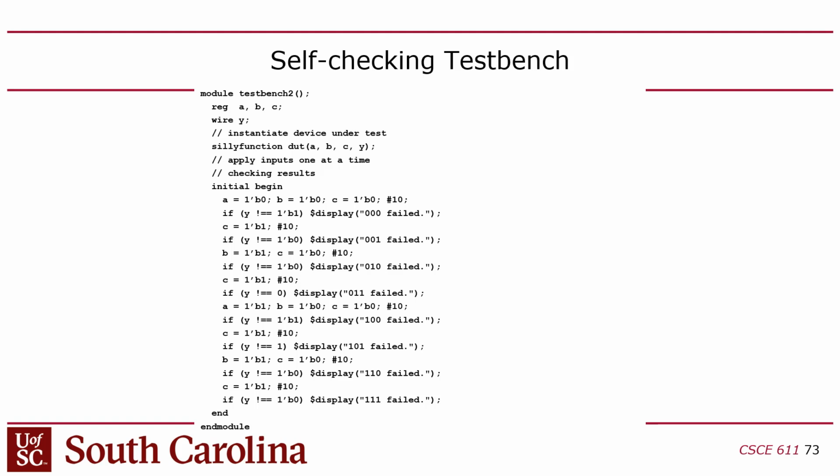When you simulate behaviors with combinational logic, it's infinitely fast, right? The circuit is infinitely fast. But it still requires a non-zero time. So the reason why we have these times in here, this hash 10, is to give it some amount of time, but it doesn't matter how much time, for the outputs to update after you change the inputs, right?